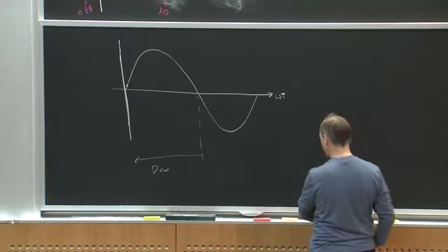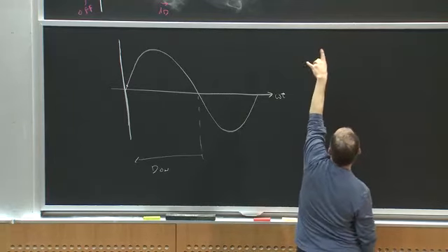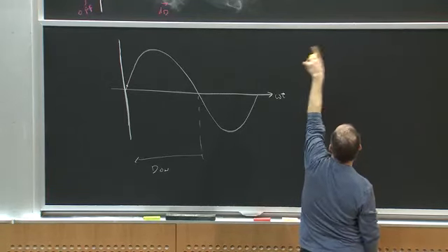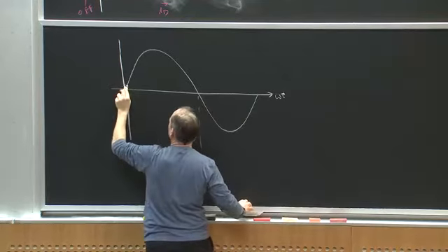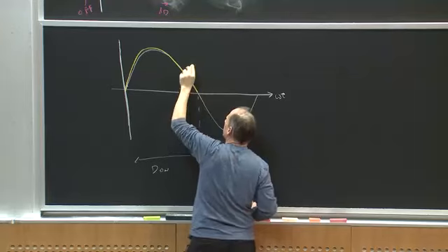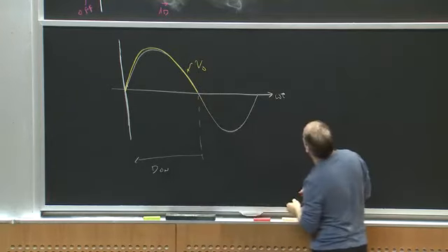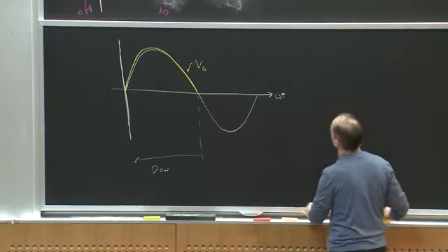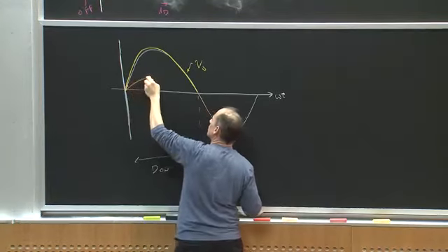And so I would get V out looking exactly like Vd, because if I look at the top assumed circuit, Vs sine omega t is applied directly across V out, and it looks like this. Right, here's V out. And what would the diode current look like? ID, well, ID is just Vs over R, so it would do something like this. Right?